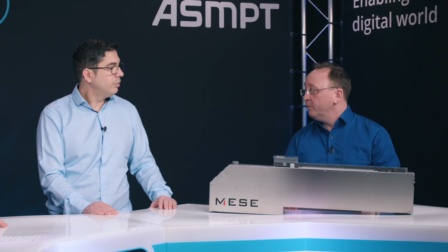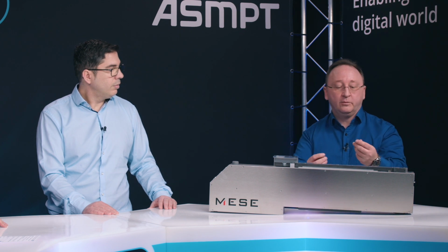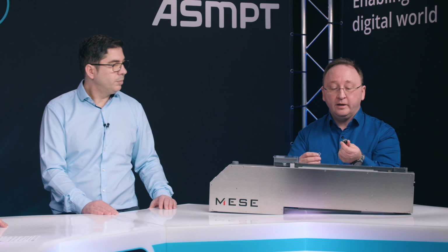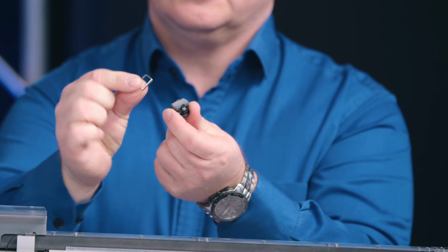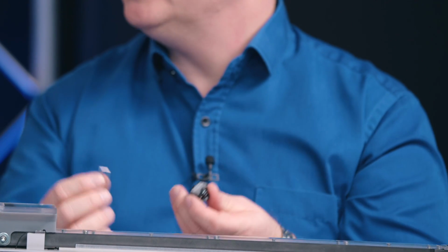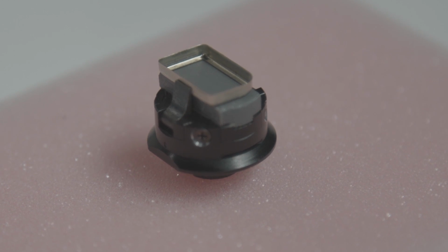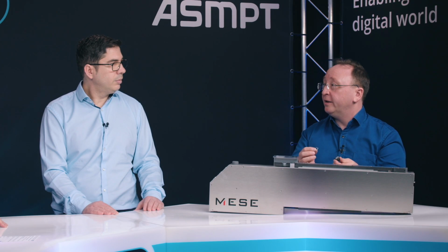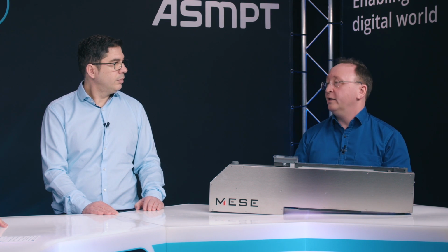We also have now grippers available for the CPP head. I took here also a sample with me. So here you can see the gripper, and here you can see the dedicated component for this one. It's a small shield. Like this, now components which had to be placed before by the twin head, because before only grippers were available for the twin head, can now be placed by the CPP head. And like this, we have again a nice line and head balancing.